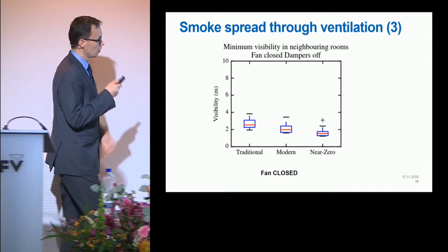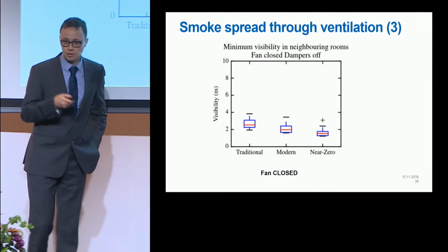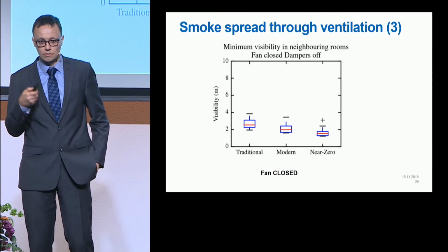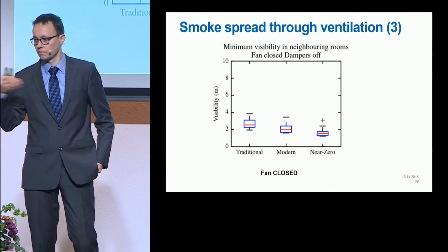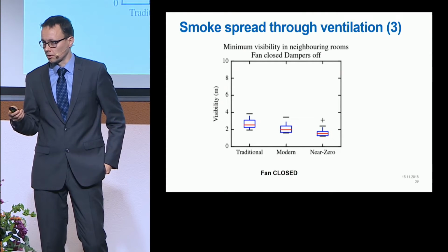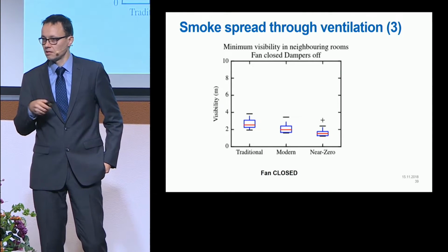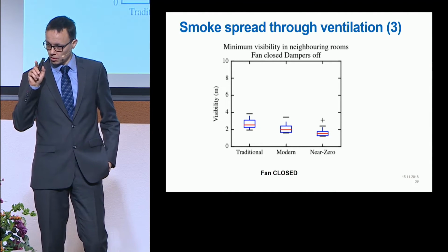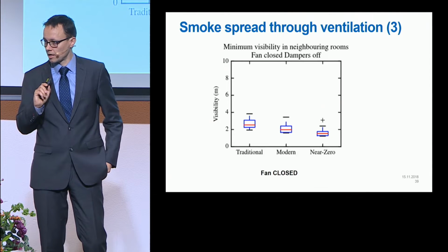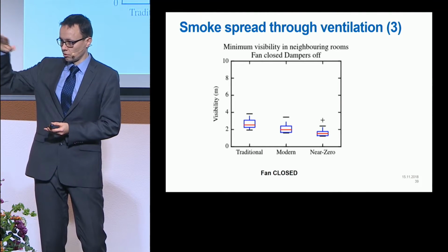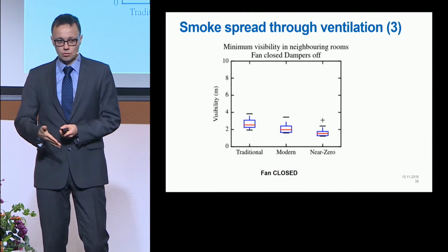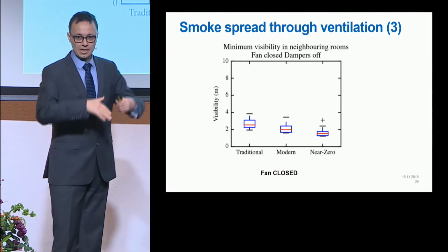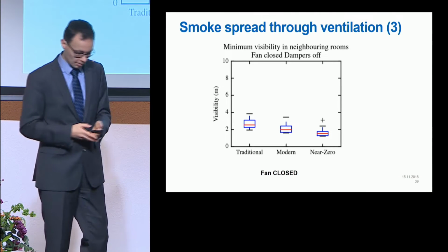And this is due to the fact that the modern air handling units of the ventilation systems have a lot of logic in them, and they have a lot of protection systems, and many of them, at least in Finland, operate in such a way that if you turn off the fan, it will actually close the external valves for weather protection. And it will mechanically close itself, which is not a good idea.